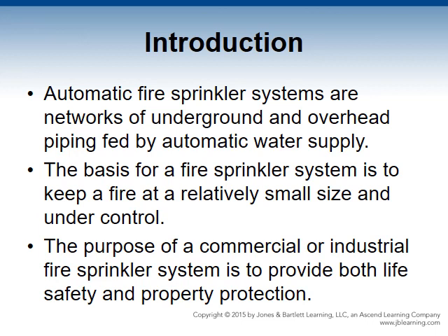The basis for fire sprinkler system design is to keep a fire at relatively small size and under control, not necessarily to extinguish it. So, for example, a fire starts in a bathroom after a social event. The fire grows quickly, and as heat rises, the sprinkler head nearest the fire activates. However, the growth of the fire is rapid, and a second head activates. At this point, approximately 5 minutes from the start of the fire, the room falls below the remaining sprinkler head's activation temperature, so no other heads activate.